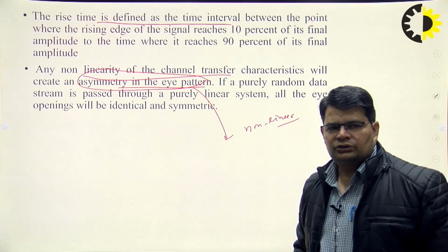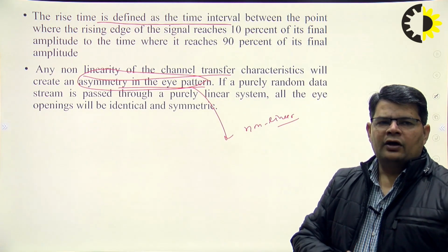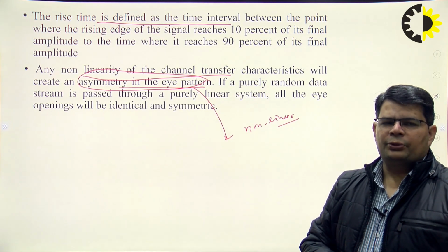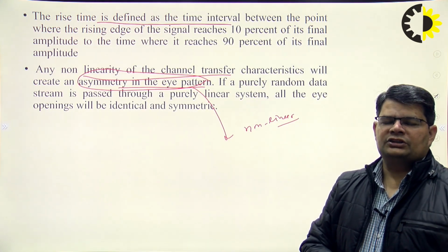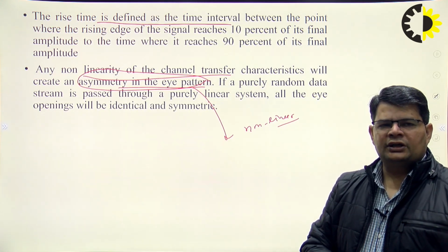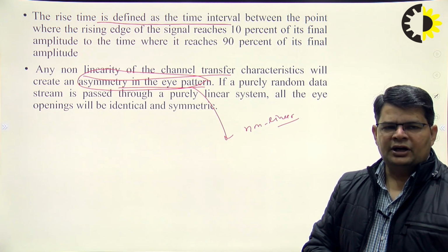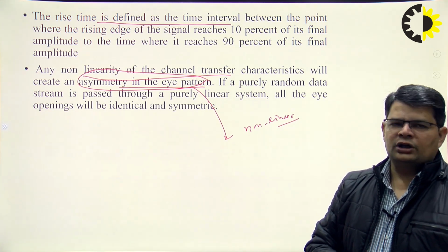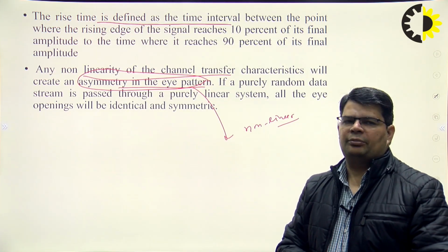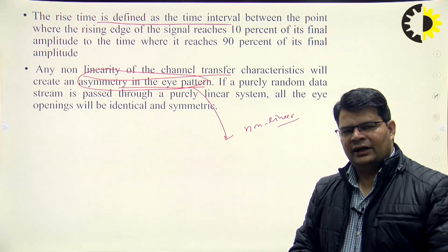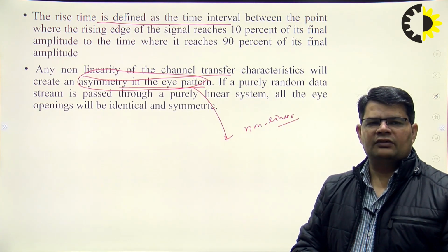So in this way, we can analyze the performance of a wired communication system, for example, an optical communication system, using the eye diagram or eye pattern, which is simply a graph obtained in the time domain when the system under test is connected with the standard BER test equipment, and on the display of that device we can have the eye diagram or eye pattern. It is called an eye diagram because of its similarity in shape or functionality with the human eye.